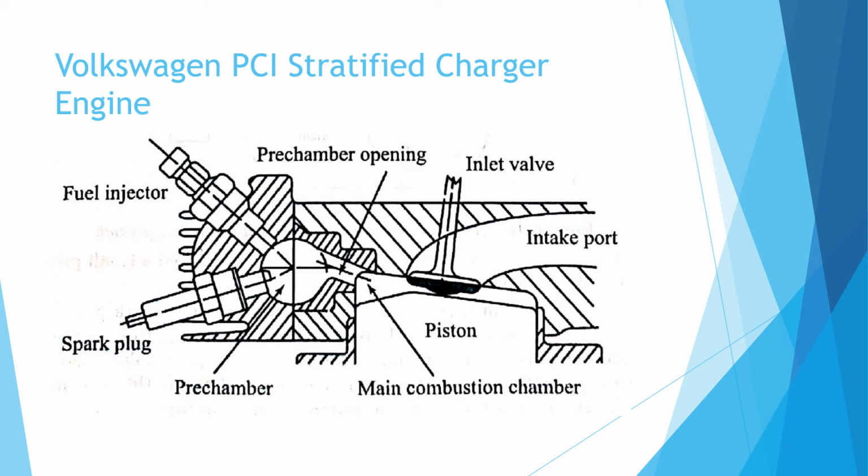The injection nozzle and spark plug are arranged in sequence in the flow direction during the compression. It is for the purpose of the spark plug to receive a mixture of incoming air with fuel already dispersed in air. This is expected to avoid over-enrichment at the spark plug.